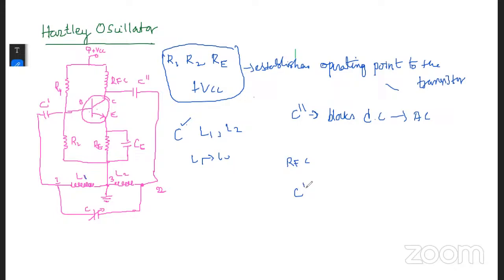So this capacitor and resistor R2, whichever we have, produce a self-biased base voltage, with capacitor CE, which provides an AC ground and prevents any signal degeneration here. It also provides some temperature stabilization.